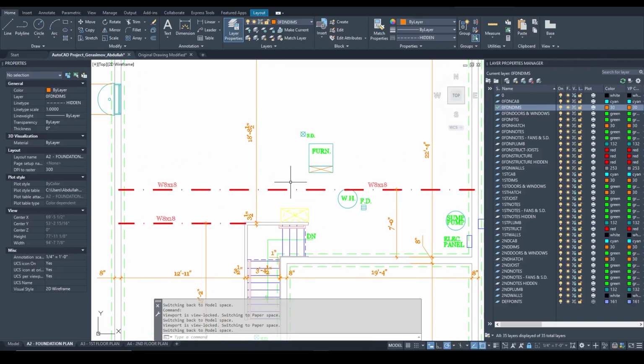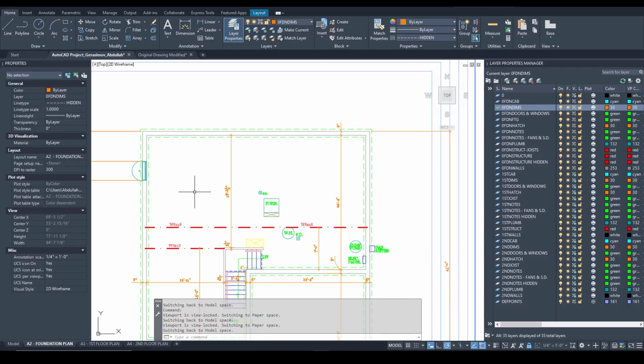Now, what W8 by 18 means is the steel. It is a steel beam. Both of them are of the same size, and they will be spaced out. It's not a continuous beam. The one that is shorter is going to be a solid one, but the one that is longer will consist of several beams. And we're going to put columns in the middle of this longer beam so that we can break it up. They will support the joists that will be supporting the first floor, which we will draw next.